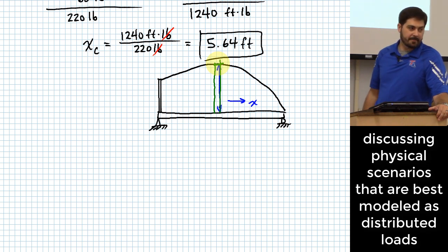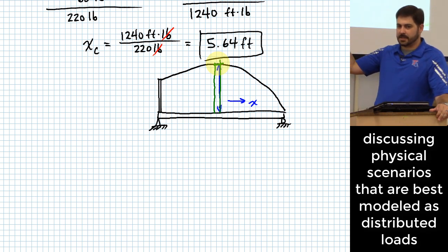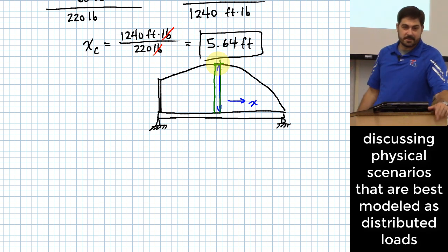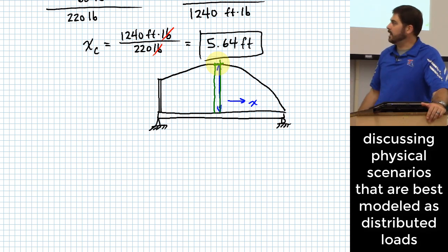And if you know the density of the thing being stacked, what does that give you for that little column? Mass or weight, depending on whether you're talking about a true density versus a specific weight. So that means for that little column, you have a weight, you can integrate that over the entire length and figure out the centroid of that area, and you can end up finding a location where you should lump all of that load to get the same reactions at the supports.